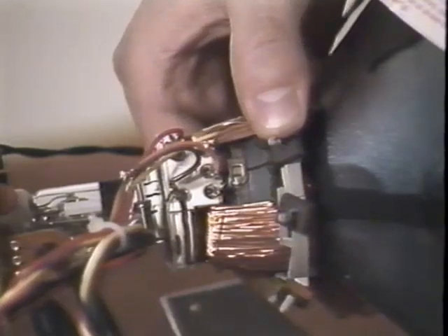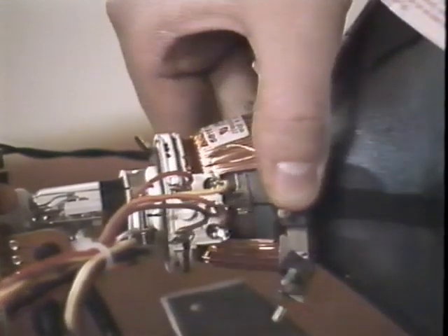The yoke rests on the outside of the tube where the neck widens into the bell. It is important to orient the yoke correctly. If you do not, the display area will be slanted or, in extreme cases, upside down. Remember that high voltage spikes pass through the yoke. Be careful not to touch the windings during service.